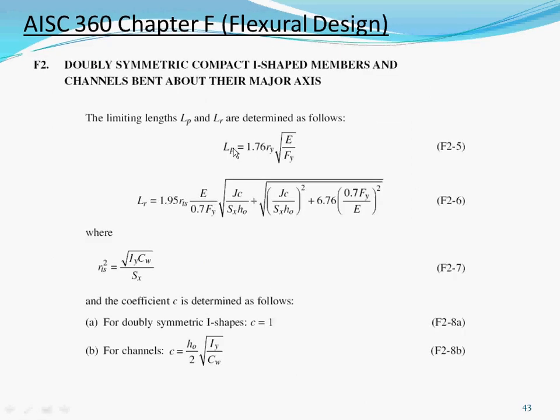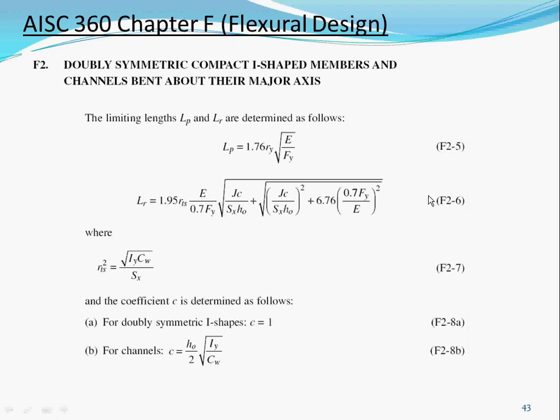Like I said, the equations to calculate Lp and the equations to calculate Lr are just right below, in 2.4 and 2.3. So 2.5 is to calculate Lp. So plug in and check again. And then remember, this was 0.08 or so for moment frame bracing. So you can tell the difference between what's required for Lp, to get the Lp distance, versus the bracing. We'll take a look at it later.